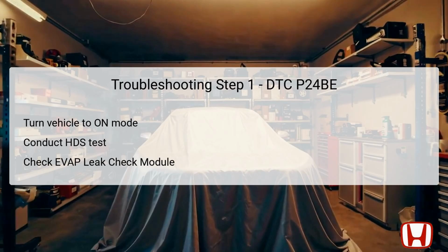If the HDS indicates the result is not okay, this signals that the failure is present and should be replicated. Following this confirmation, it is essential to delve deeper into the diagnostic procedures to pinpoint the exact cause of the low voltage condition affecting the canister changeover valve control circuit.